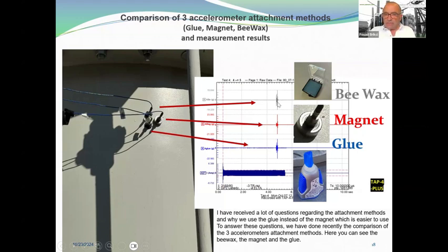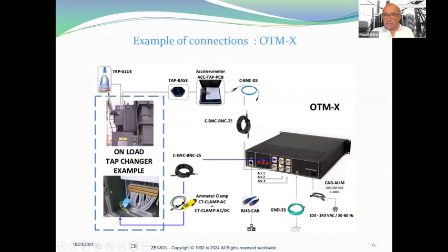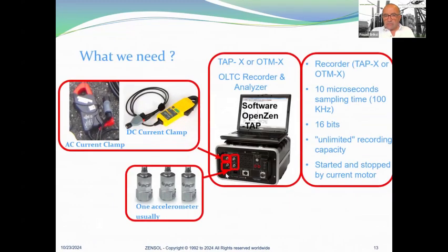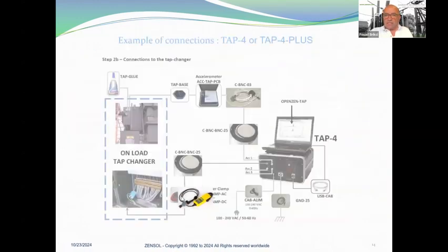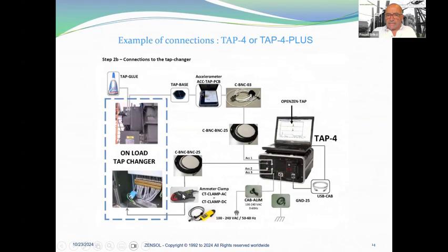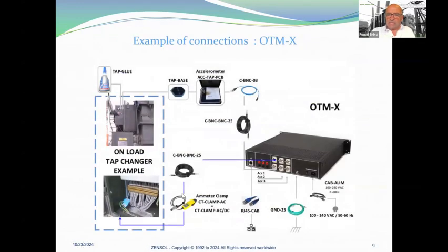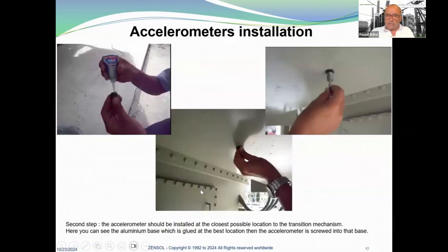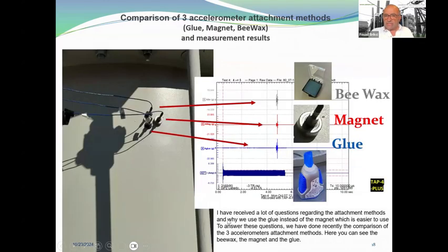We have done the recording of these three signals. In our tap changer, we are able to put, as I told you, three accelerometers, so it was easy to compare exactly the signals produced by these three recordings in one recording.